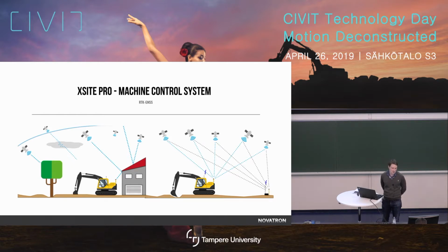For example, there can be a base station on the worksite provided by us, and the location of that base station is known. And when we know the location of that base station, we can recalculate that the base station should actually be here, but the GNSS data shows that it's actually in here. So all the GNSS devices in that worksite, we need to redo this basic mapping from this place to this place. So actually the correction is also location related, and that's why sometimes you might need a local base station